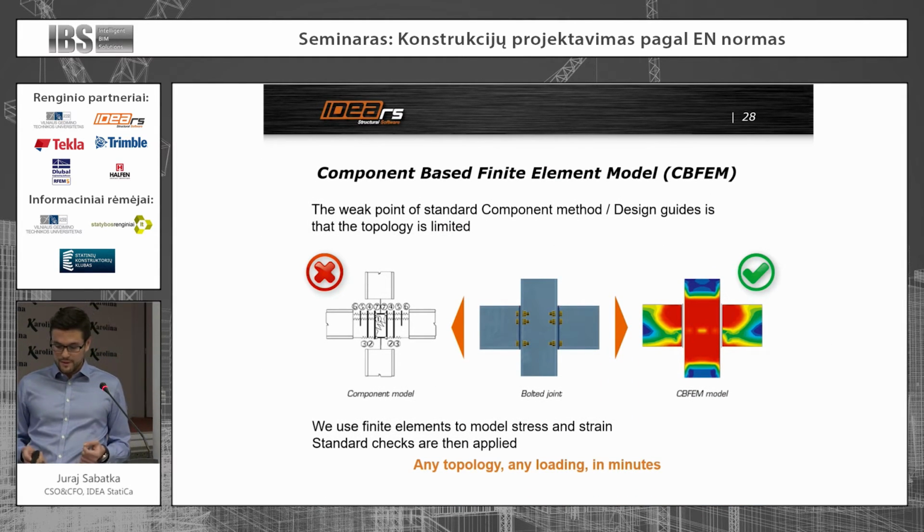And this enables us to adjust the design if necessary. Now back to the method inside. It's called CBFEM, Component-Based Finite Element Model, and it's a synergy of 2 well-known procedures: finite elements, which we use every day for beams and whole structures, and the component method, the checks by the codes, equations. So we merely mix them up.